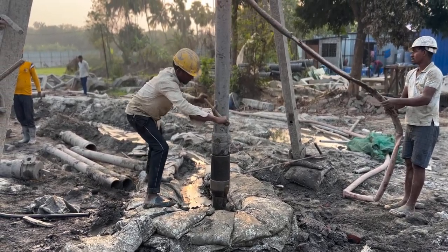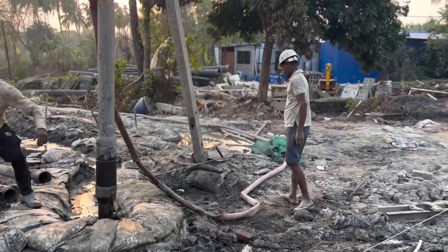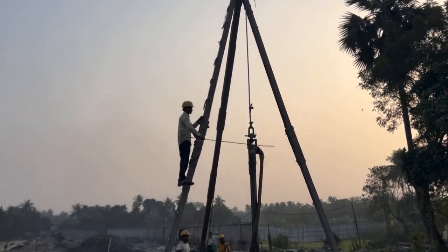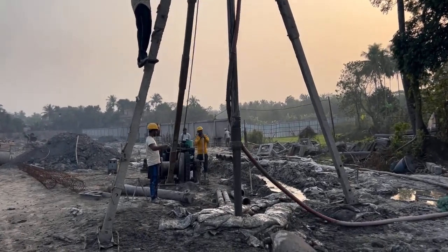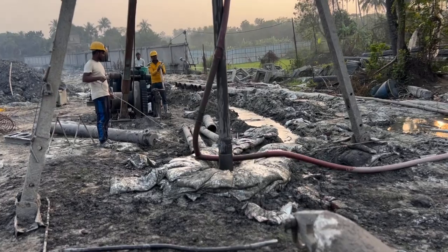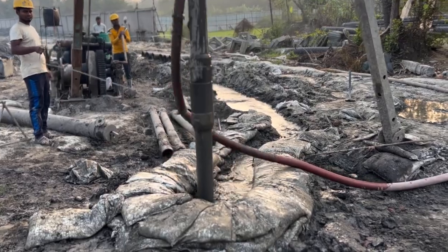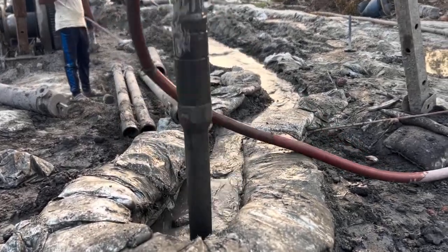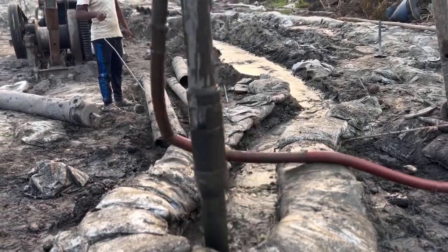Now we need to know the relevant IS code. Whenever we are working in India, we need to know the relevant IS code for the bore pile. That is IS 2911 Part 1 Section 2, 2010, the code of practice for design and construction of pile foundation, that is bored cast in situ pile. And IS 456, which we all know, is the code of practice for plain and reinforced concrete. And IS 10262:2019 is the guideline for concrete mix design. So these three codes we need to use whenever we are dealing with the DMC bore pile.